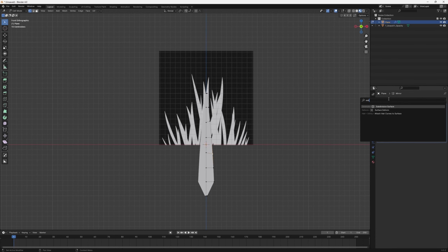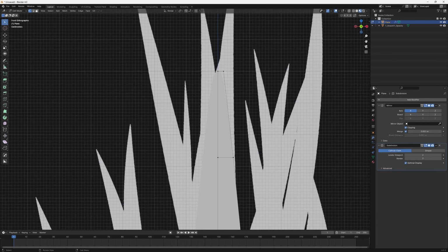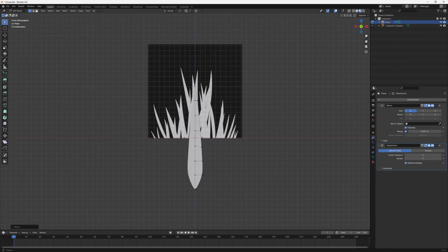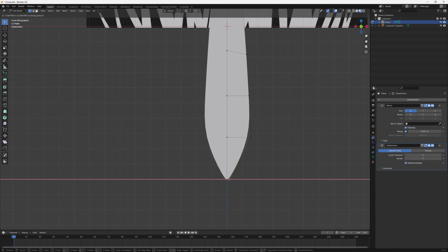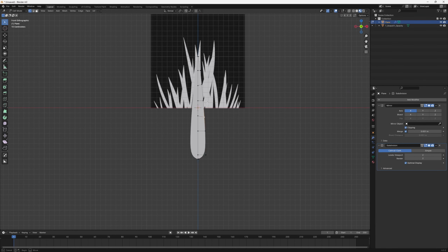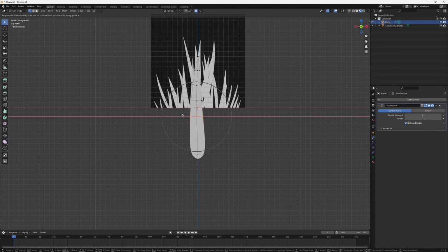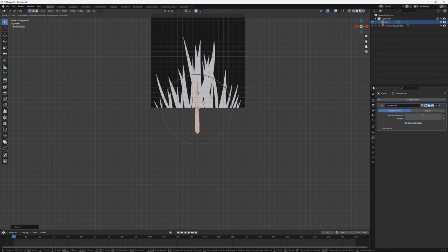And so because this is for texture baking purposes, we can actually subdivide this for our texture creation because we are not worried about poly count right now. Drag it down, and I'll use proportional editing after I apply the mirror modifier to just give it a nice little bend. And then by scaling it down, we could just start placing it around.